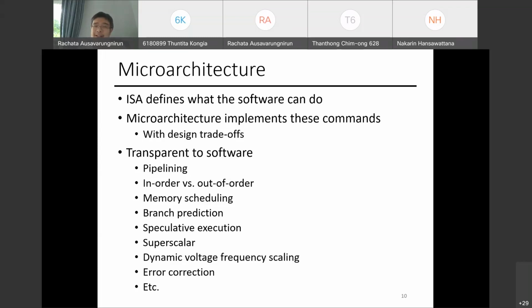I have to tell you a fun fact, everyone did that. Intel does that, AMD does that. It's like a default. This is basically textbook dynamic voltage frequency scaling. Do you want your battery to drain in 3 hours or do you want your battery to drain in 6 hours? You probably want the latter, right? The lawsuit basically looked at the wording, like, oh, you need to tell the user that hey, it's not as fast as before. Yeah, obviously, right? So just be aware these things are done.